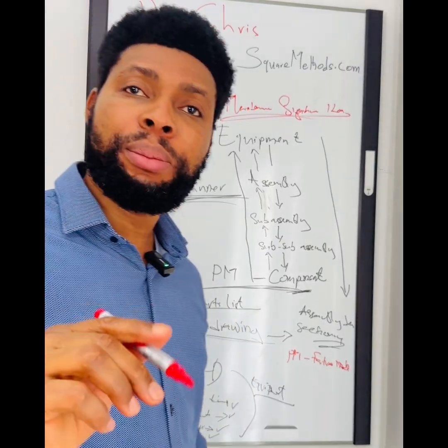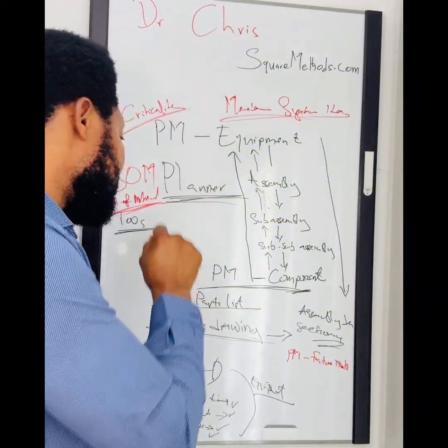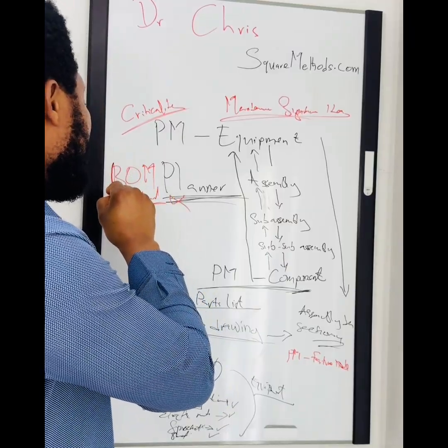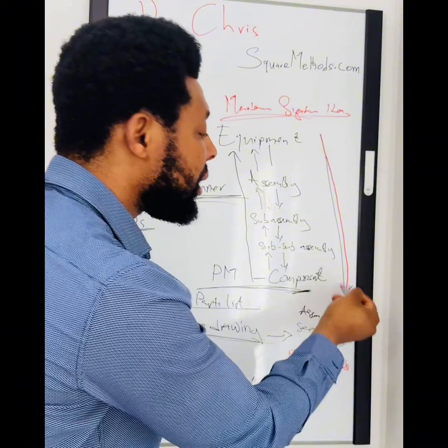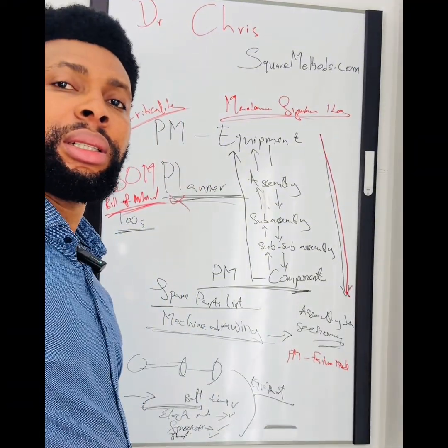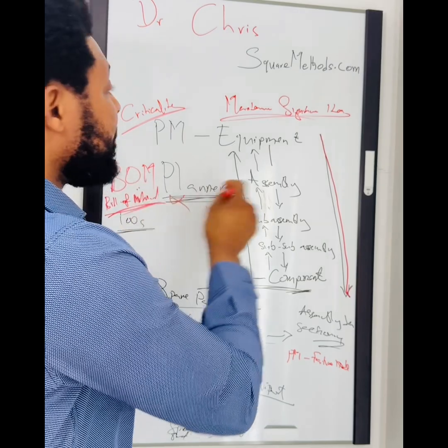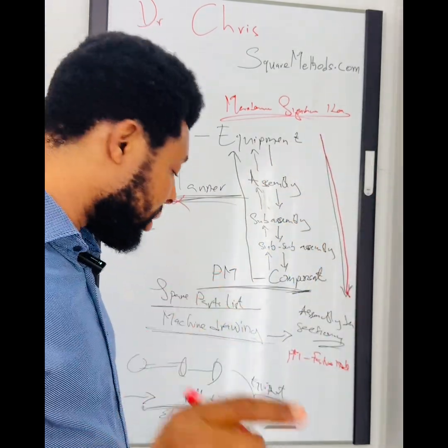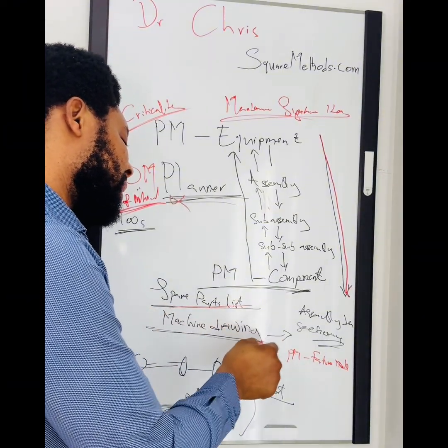So you are expected to have a maintenance plan and task list for your BOM list. This BOM list should come from breaking the machine down into components. And what is going to help you to do that is your spare parts list and your machine drawing,